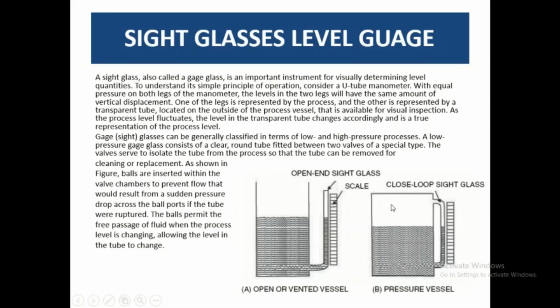On the other hand, in the inner part, where the vacant part is, the pressure is much lower. So it will show less reading of the liquid as compared to the actual level up to which the material is filled in the equipment.